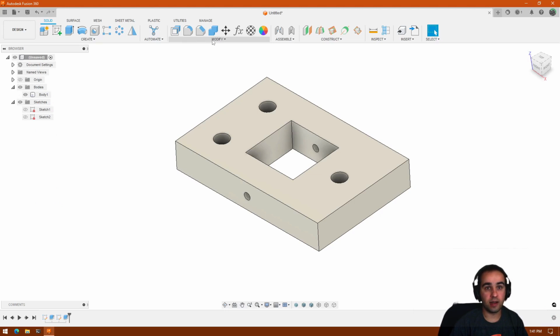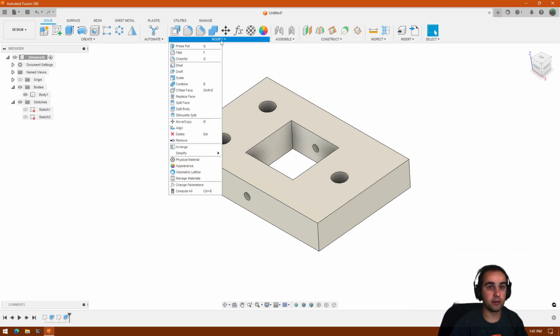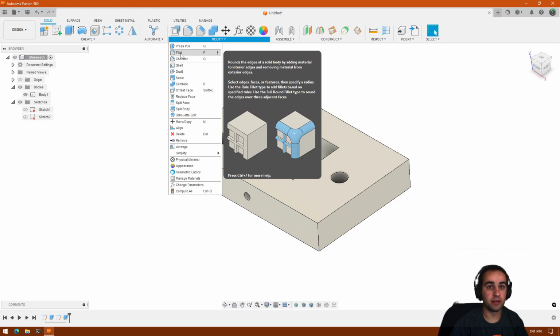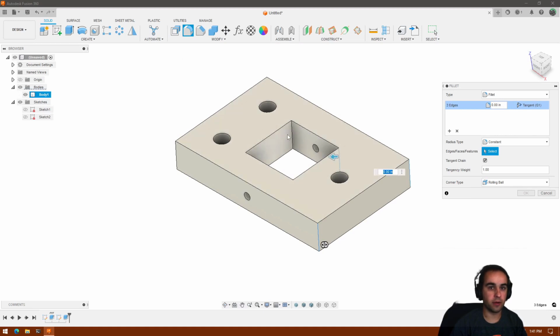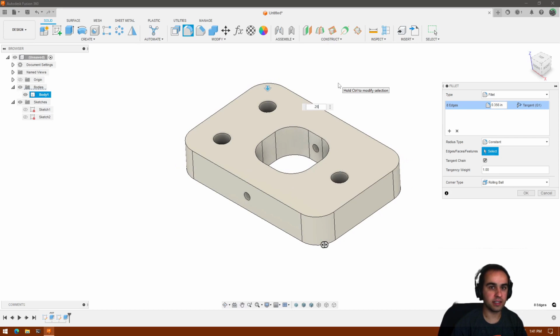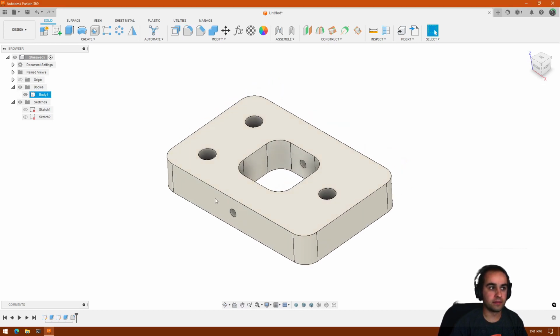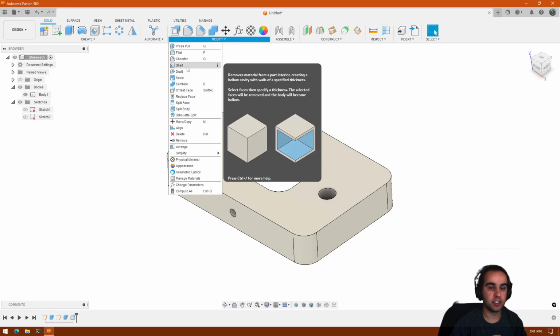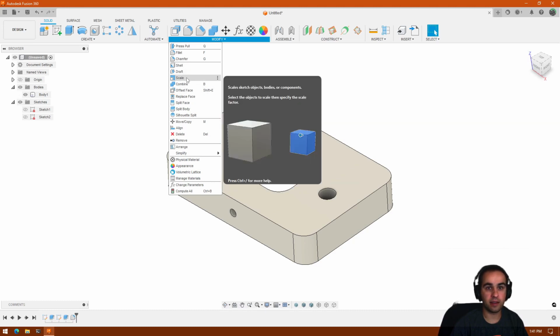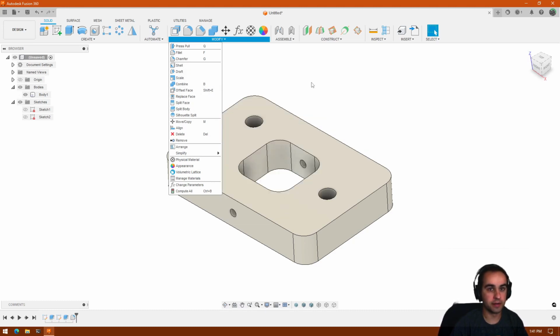There's also a large set of operations you can use to modify a part. So, for example, a common one would be a fillet operation, which I'll go ahead and select, which lets you pick some corners in your part, both internal or external corners. So I'll select all these, and then give them a radius, say 1/4 inch. You can see that popped up in our timeline down here. And there's many other options you can explore here as well. Chamfer for beveled corners, shell to make something a thin shell, even scaling a part up or down or splitting it along a plane.